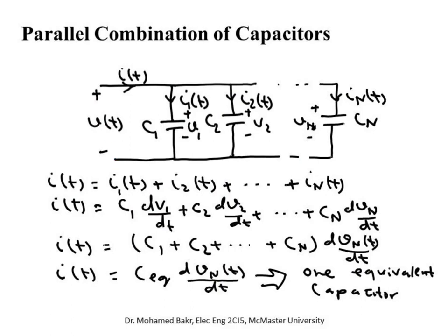So these capacitors which are connected in parallel look like one capacitor, because this is the equation of a capacitance. And the value of this capacitance is their sum, C1 plus C2 up to Cn. And this is surprising. This is very different from the case of resistors. So when you connect capacitors in parallel, you use the same law you use for resistors in series. We add the value of the capacitances. So you can see C equivalent is C1 plus C2 up to Cn.